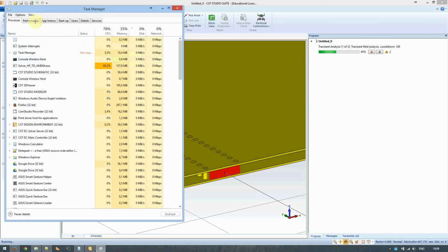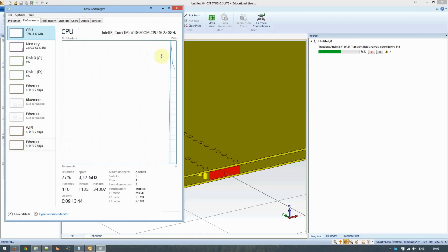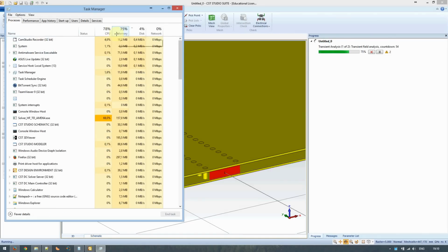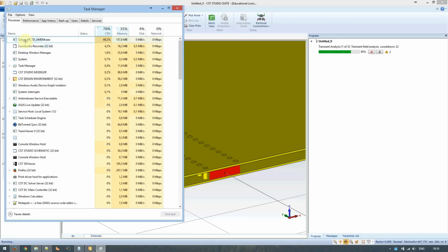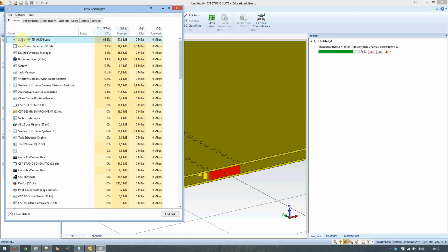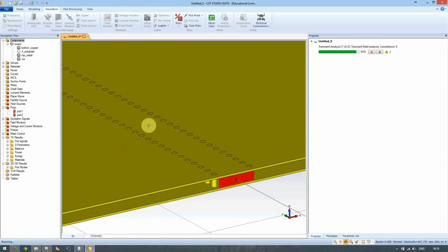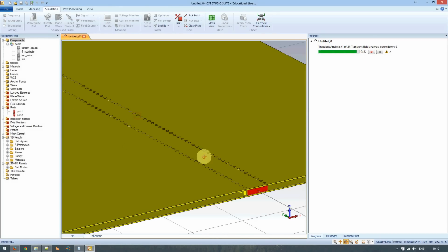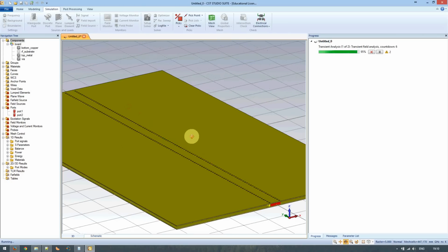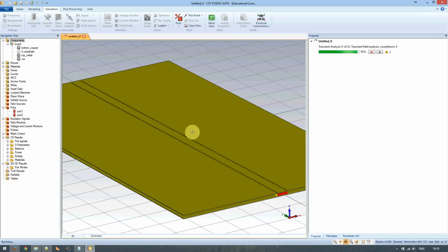With one exception though, performance. So you see the CPU usage graph is quite high and it's using a lot of memory as well. Yeah, it's using the transient solver in 64-bit mode. Okay, so transient analysis 1 of 2. It does 2 because it does 1 from each port. You can tell it to use S parameter symmetries, in which case it usually only does 1. But if you want to be really accurate, then you uncheck this option.